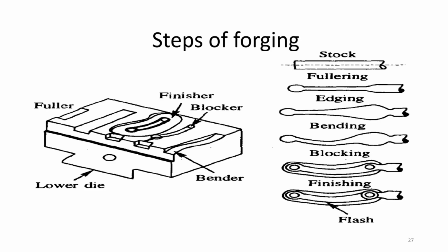For the liquid and solidification, it will be dealt with by the riser. Is that correct? Yes, liquid shrinkage will be dealt with by the riser, and solid shrinkage will be dealt with by the allowance that you provide, right? Solid shrinkage allowance.